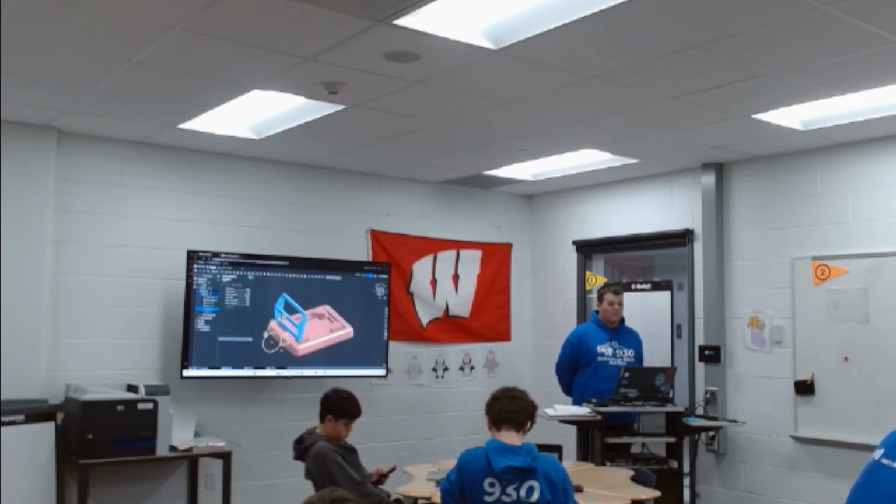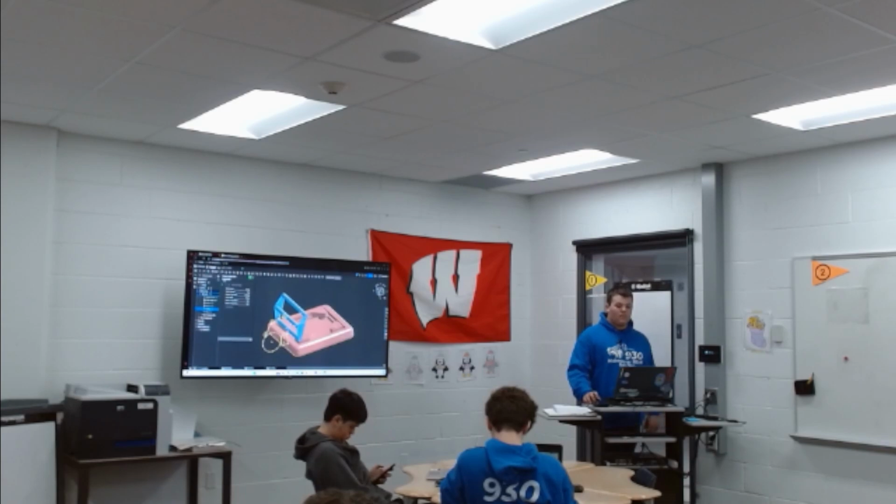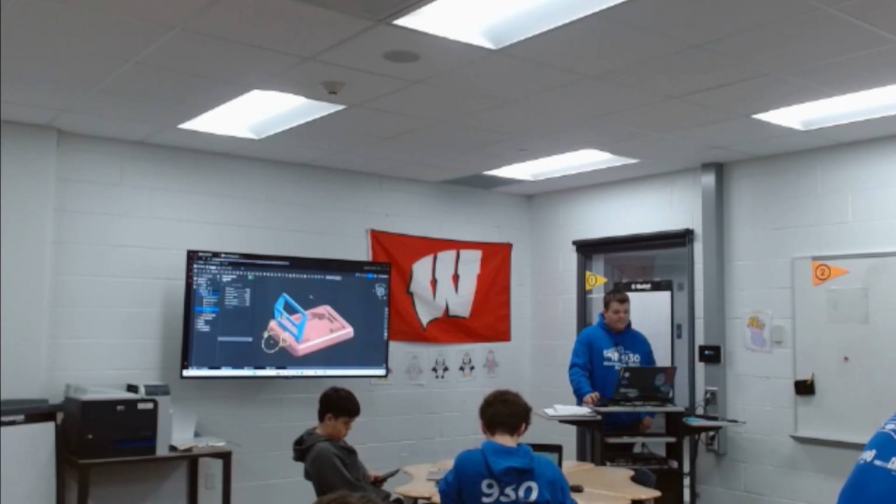Oh, looks like there's something wrong, so we can fix this manually. It's just rotate 90 degrees. You can do an offset, and then you can rotate around. In this case, you want to rotate around the y-axis. So instead of rotating around x, you should just rotate around y. And just try the rotation.